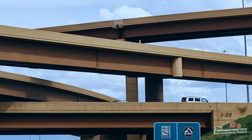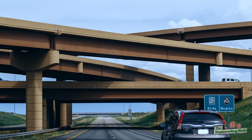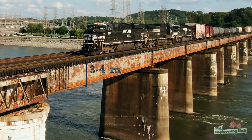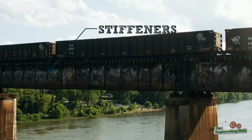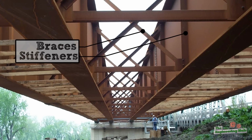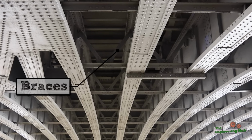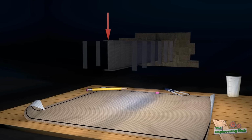One example of I-beams being taken to the extreme is something called plate girders, which are typical for highway bridges. Notice how deep the I-beams are and how they need stiffeners at regular intervals. These stiffeners are to prevent local buckling of the web. And these stiffeners, also called braces, are to prevent global buckling of the member. In these ways, buckling can be easily dealt with.